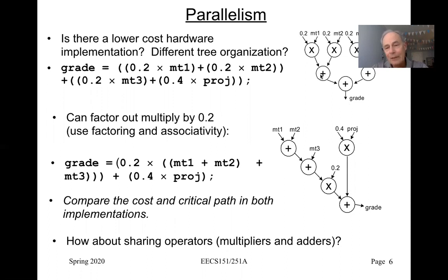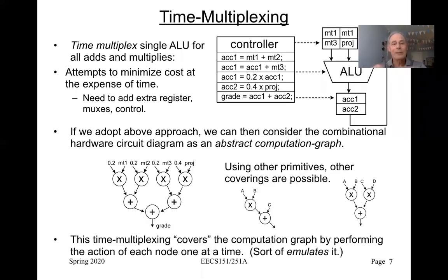The other thing we can do is expand the calculation temporally into the time domain, and that means we can make it sequential. So what we do when we optimize, or look for ways to parallelize or not, is make trade-offs to move computation between space and time. The ultimate move into time is what I showed on this next slide, where we're talking about time multiplexing. Here we take the same computation, but we do it sequentially, in time rather than in space.